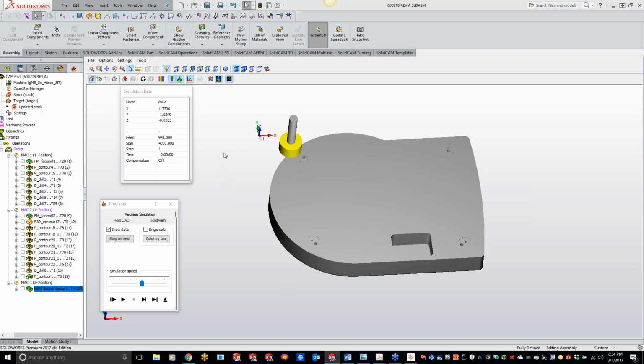And another way is you can just create a quick little dummy program to get rid of those slugs. And then you can just suppress the G code so it doesn't ever show when you actually post it out on the code.